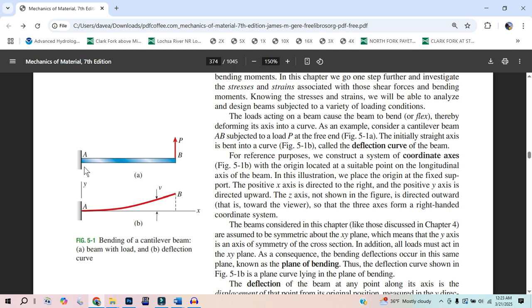No, it's going to shear. And so shear is only half as strong. So you're not going to get 58,000. You're going to get half that, 29. So maybe we could take that semi and break through.